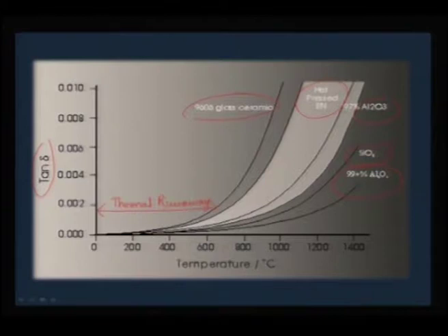Only after the sample reaches say 600 or 700 degrees centigrade, will you be able to scale up or maximize the coupling, and therefore when you look at the insulating oxides, or ceramics in general, one of the important things that we need to understand is it is not as quick and fast as the solution route. Therefore, this thermal runaway is a very important parameter when we are looking at solids when they interact with matter. So, I will take you through some of the examples from now on.